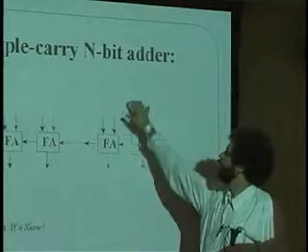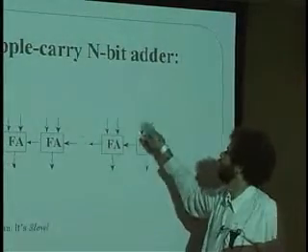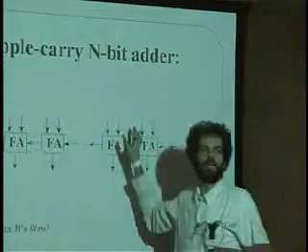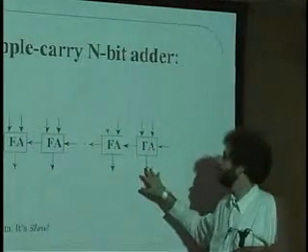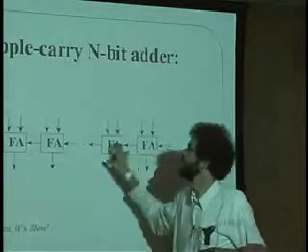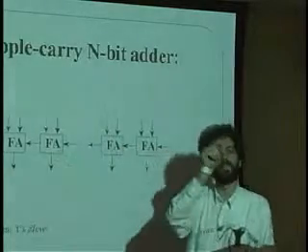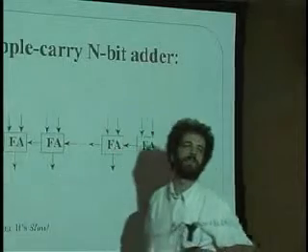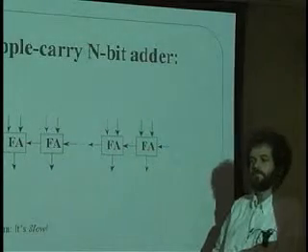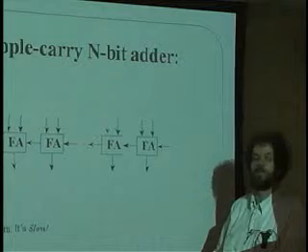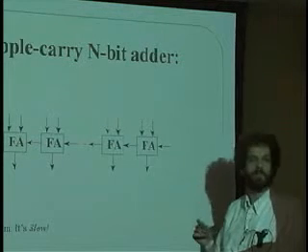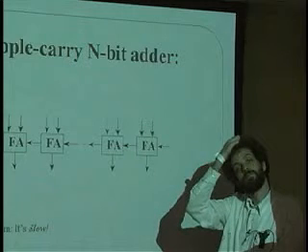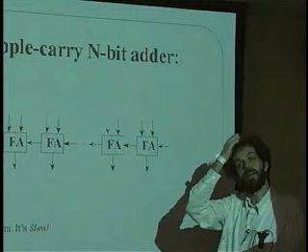And what would the carry-out of the left-hand bit mean? So let's say I fed in 32 bits of A, 1, 2, all the way to 31 and 32, and also B, and I got a 32-bit number out of here, and I had 32 full adder 1-bit slices. Well, what would it mean for the carry-out to be high? Isn't that going to depend what our sign is? That's absolutely right. So if the numbers are positive and you get a carry-out, what does it mean? The number got too big, right?